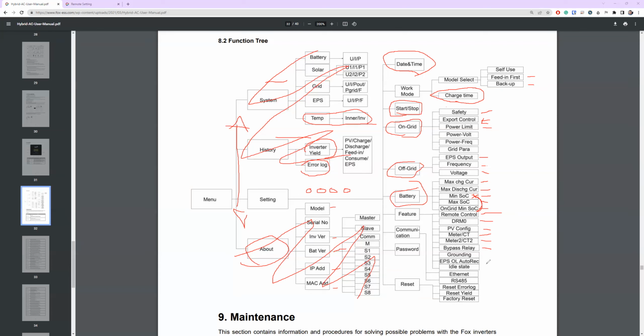It's riddled with regulation, and an incorrectly configured EPS circuit can be dangerous. Grounding is required, and that's what this option is. If you're using EPS, in the UK, you're required to install an additional earth stake or screw. You need additional earths installed, and that's to protect the circuits. And instead of using the inverter's earth, which is coming from your supply, which most of them are CPC and neutral bonded, so that's coming straight out of your DNO, your distributor.